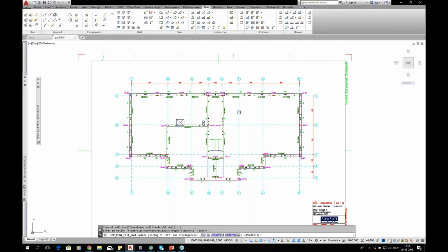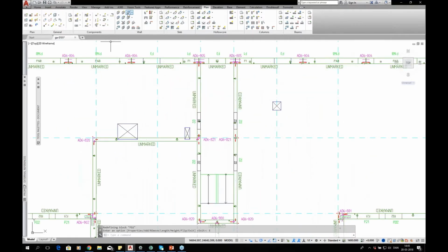And then the system now rolls through every single element, puts on the connections to the sides of the windows to avoid these cold bridges, all these connections we've added, and end caps as we call it in IMPACT. Recalculates the center of gravity for each single element, recalculates the position of the mounting bracings, recalculates the positioning of the lifters. And if you really look closely, you can actually see it moving through the elements. It's somewhere down the right corner right now, recalculating the elements. And there we go, it actually finished with all the sandwich panels. And we'll do the same thing for the solid wall panels here.